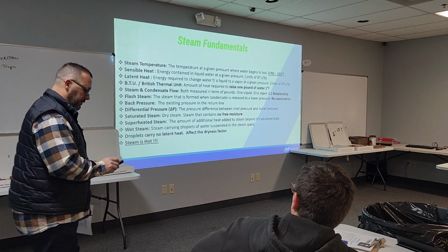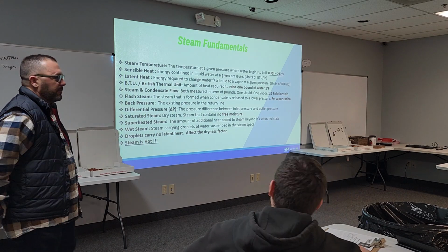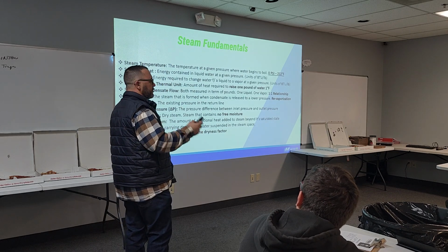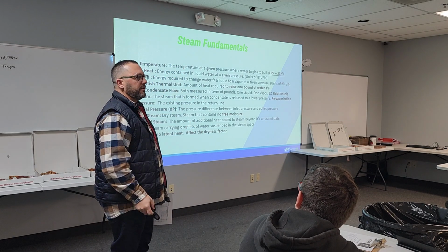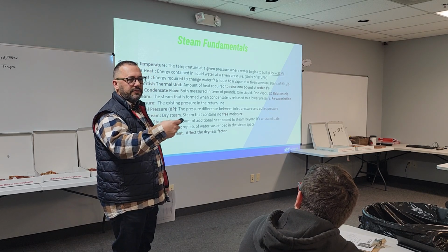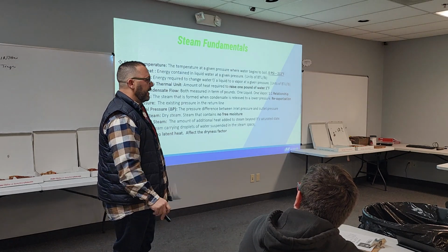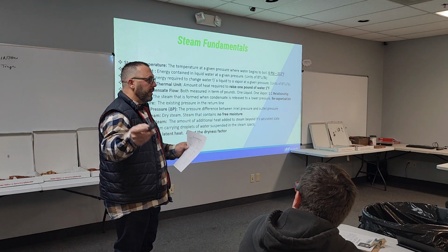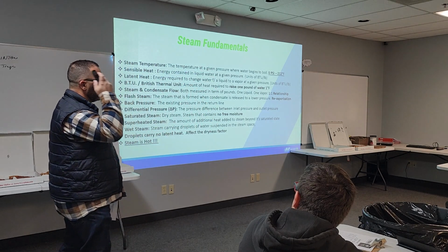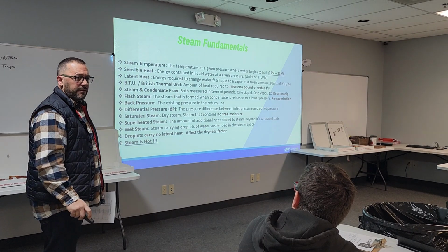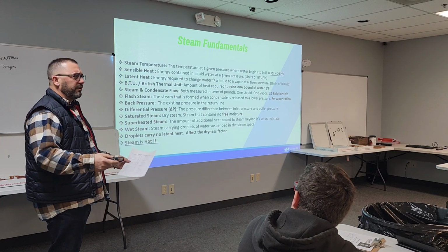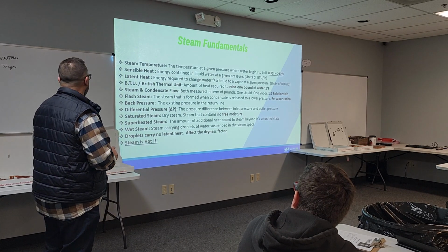It's just actually flash. Back pressure, not talking about my back today, even though I'm feeling some back there. Back pressure is just the existing pressure in a return line. If we're going up 20 feet, it's real safe in the field to assume that's 10 PSI of back pressure. It's actually every 28 inches is 1 PSI, but when we're walking a plant off, we've got a 10-foot lift there, a 20-foot over here, and many times, because nobody has pressure gauges anymore, and when they do, usually they're broke, we have to kind of figure things out. It's frequently in the field.